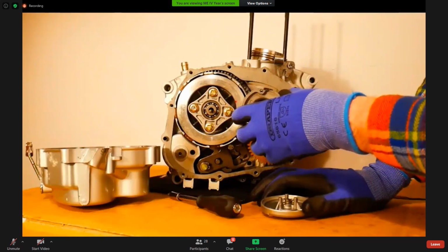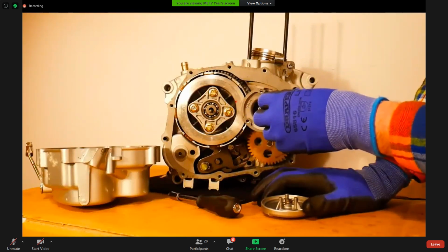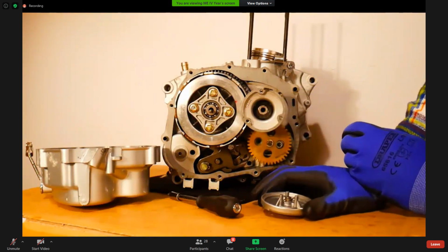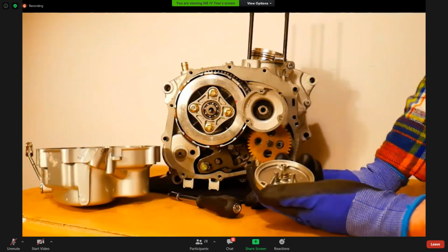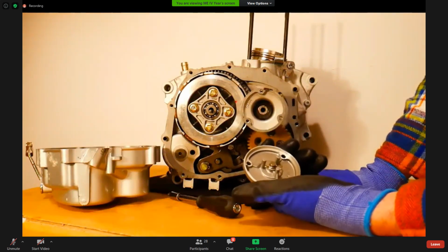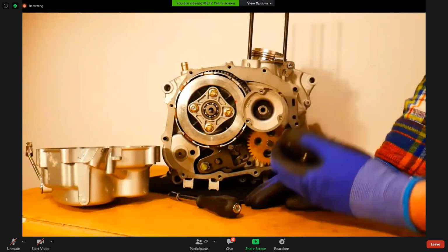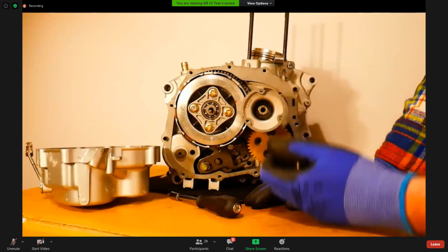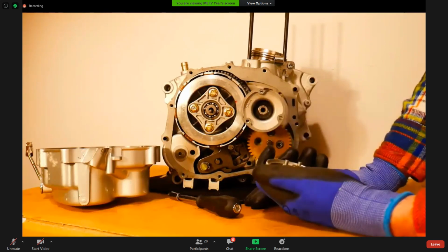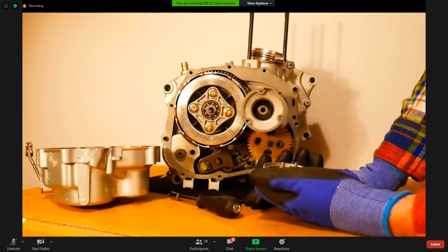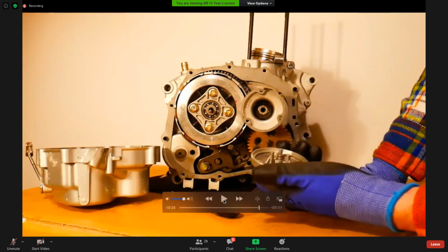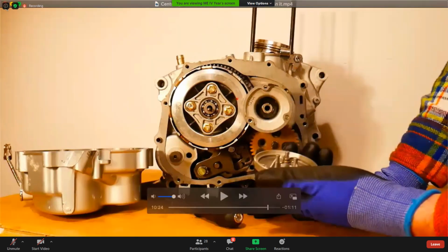Just lastly to note that there is a little gasket, which you can kind of see peeling off here. It's just a little oil gasket, I suppose. That will have to be replaced. So we'll need to have a new oil gasket to put onto this anytime you remove this, because the gasket is going to get damaged, as it has been in this case. There's a little bit of damage here when I removed it. So that will have to be replaced. They're very cheap, probably a couple of euro at most. So that should be, it's not an expensive job to maintain. So that's the working of our centrifugal oil filter.